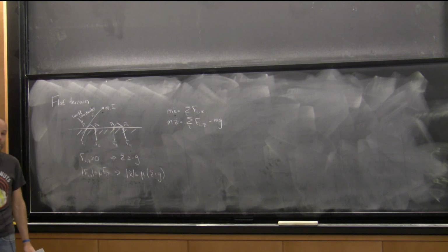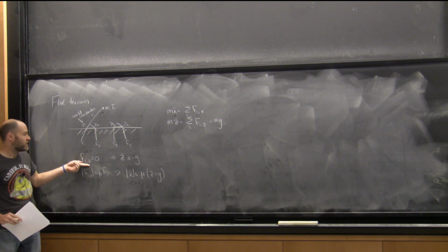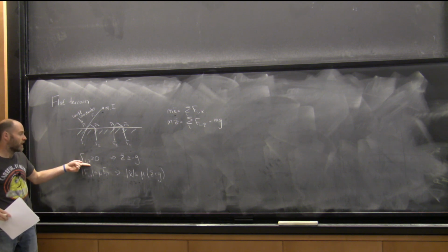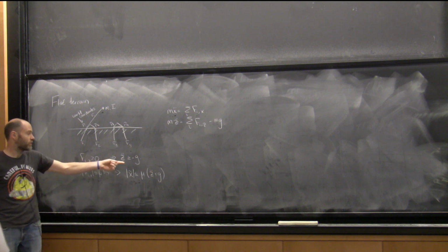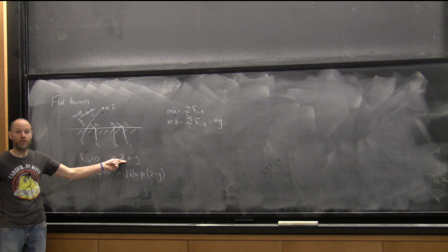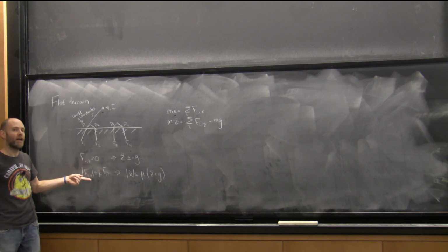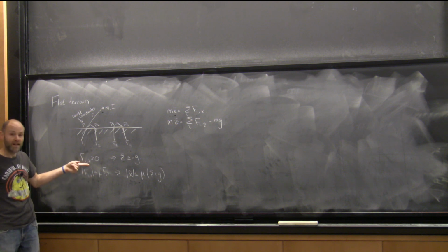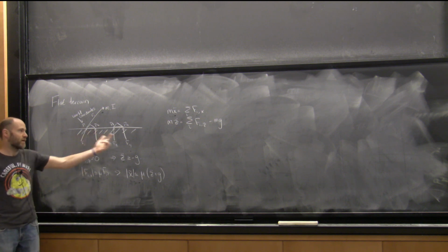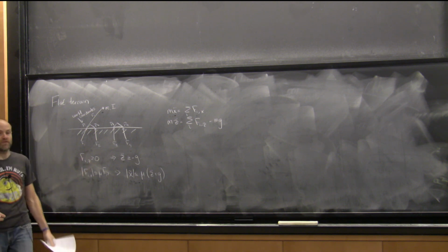Yeah. If we were coding this up, the decision variables would, for example, maybe be like fi x and fi z, right? So it depends on how you do it, but the one I'm going to work towards here is that you optimize your center of mass trajectory, x double dot, z double dot, at the same time as a surrogate for f and z, which it turns out you can summarize in a single variable instead of thinking about all of them separately. So you can jointly optimize center of mass and forces.